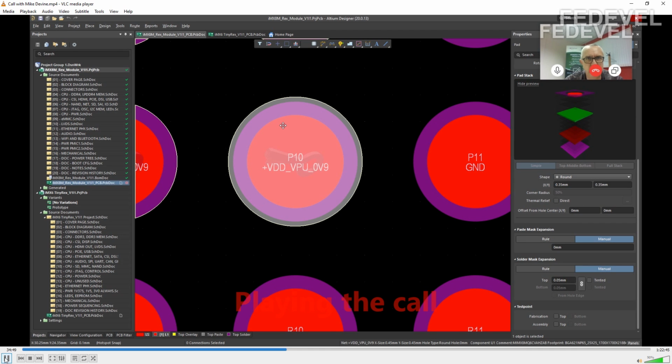If it's a buried via, we would either resin fill or copper fill all of them. Yeah. If it's a through via, we can be selective. We have to be selective anyway. Okay. Because whether it's copper filled or resin filled, the vias that we need to fill are separated on the drill program. Now, what we do see, or some customers will do, is that they will actually change the drill size. So let's just say, for instance, Robert, you've got